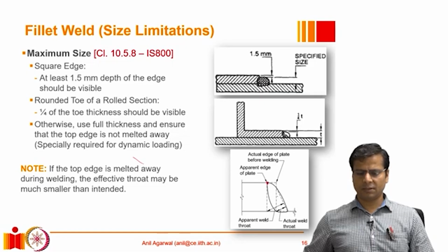The welder may imagine that if the required width was, let's say, 10 mm, they have provided 10 mm from where they can see the edge now instead of where it was before, because of it getting melted away. And if that is the situation, the actual weld that is deposited here is only this much. This situation can be approximated as a situation of an obtuse angle, right?